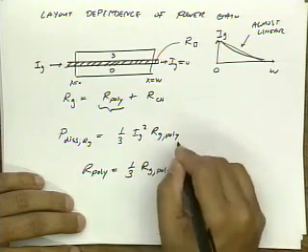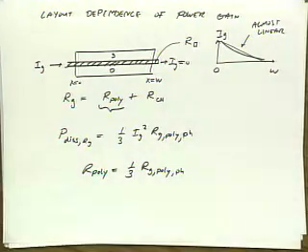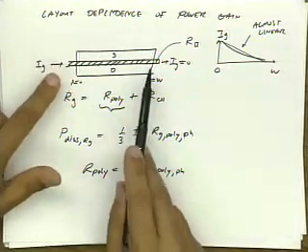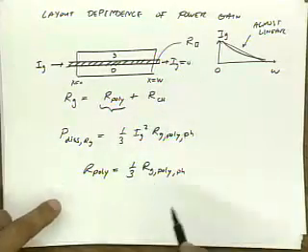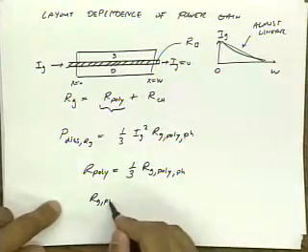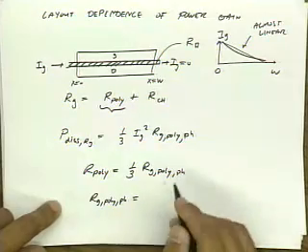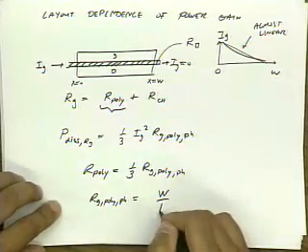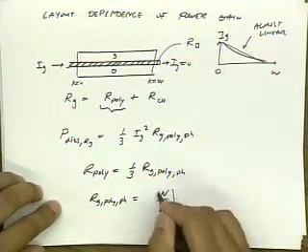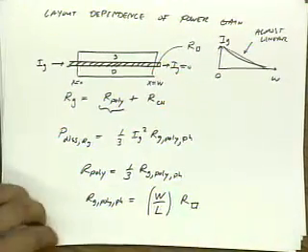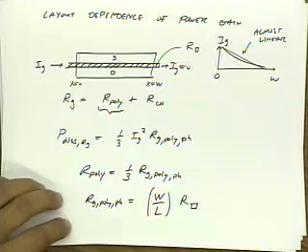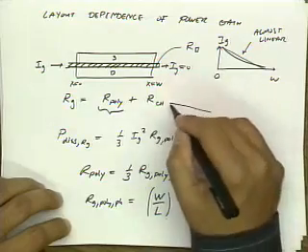Let's call this physical. Again, sorry about the notation. So this is the actual physical resistance of this, assuming you put current in uniformly. In other words, R gate poly physical is W over L times the sheet resistance. Okay? Clear? Now this term is a little bit more tricky.